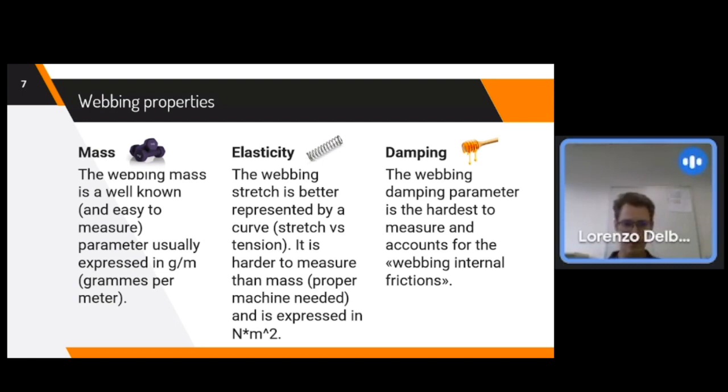When new slacklines come on the market, we ask, yeah, what kind is it, nylon, polyester, and so on. But what is its mass per unit meter? What is its stretch curve? Normally they say yes, but at 5 kilonewtons, how much stretch? At 10 kilonewtons, how much?